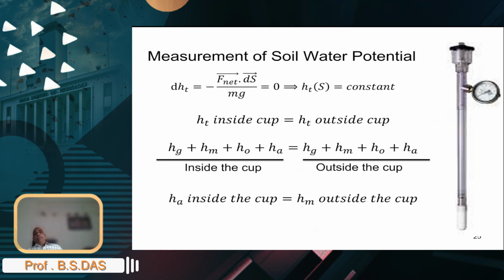And again, here is a unique opportunity. This equipment is called a tensiometer. It is basically just a hollow pipe up here with an opening. You could fill this pipe with water and cap it, closely sealing it. At the bottom, you have a porous ceramic cup.